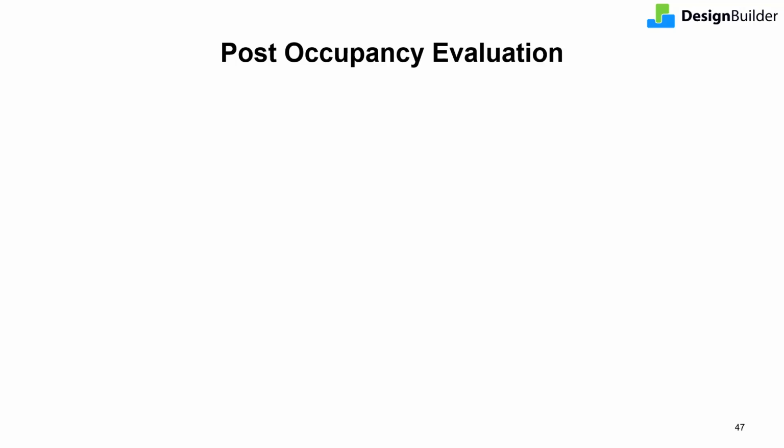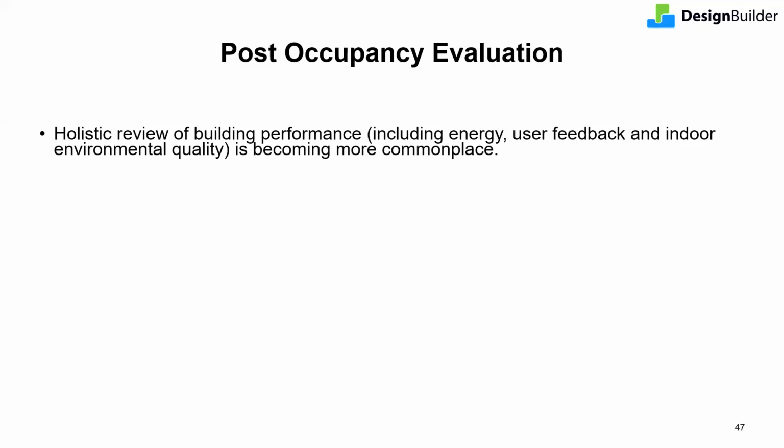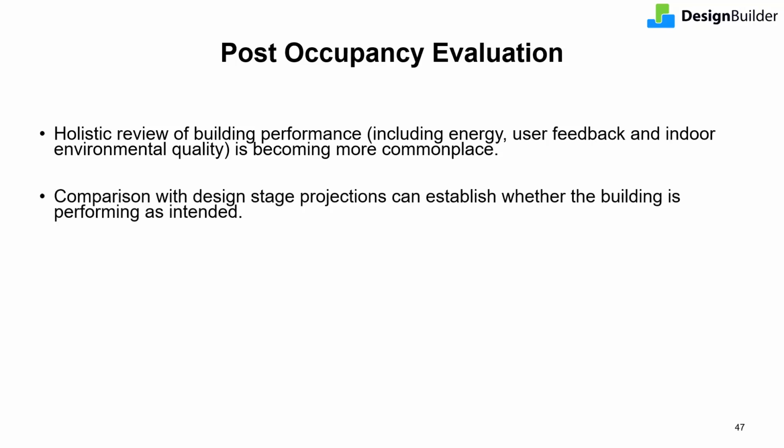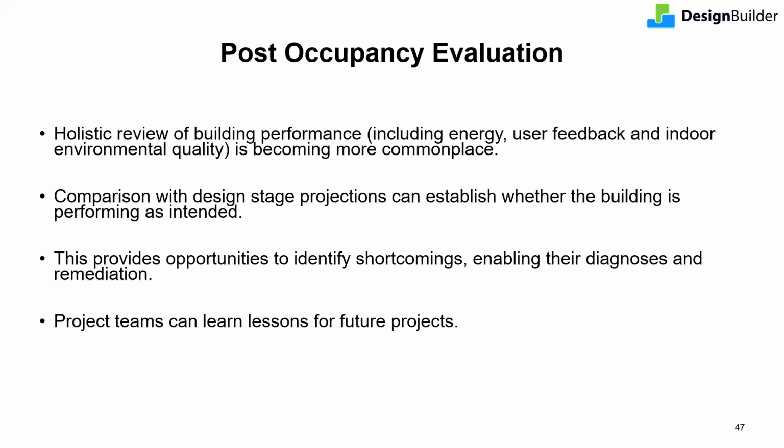So, regularly reviewing energy performance of any building once it's occupied is a vital element in achieving and maintaining high levels of performance. In the coming years, post-occupancy evaluation is expected to become more commonplace. Post-occupancy evaluation allows holistic comparison of building performance with design stage intents and building targets to establish whether the building is performing as intended. This provides opportunities to identify shortcomings and enables their diagnosis and remediation, for project teams to learn lessons for the future.